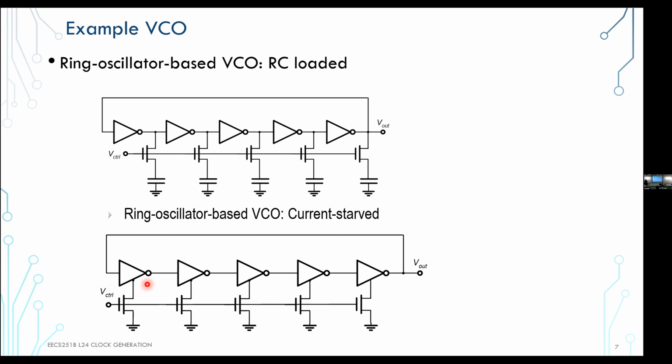There are other ways to build an oscillator. For example, I could build an RLC circuit or LC, right, and active. Those are typically rarer in big digital designs, simply because you need area for an inductor, you need to block everything out. And at high frequency, the jitter is much smaller in those types of LC oscillators than in these ones, as we'll see. But you're not running clock frequencies so high that you really need that type of oscillator.